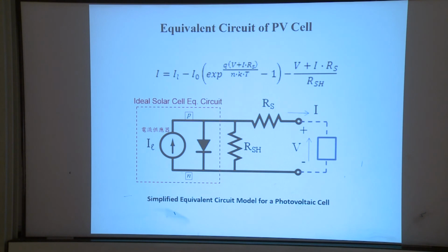Okay, so after connecting that, the voltage and current applied on the load will be described by this equation. This one is very familiar, right? I know this is the diode equation, exponential qV over kT minus 1.